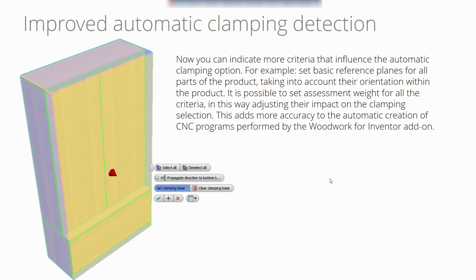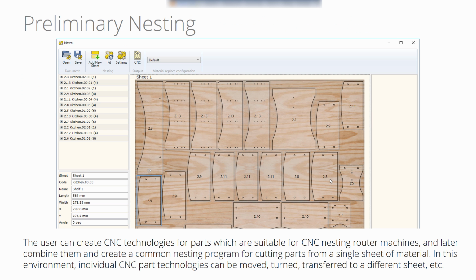There is a weight system, or a priority system, which allows you to say, for instance, keep the holes as near as possible to the zero coordinate of the CNC machine, or place pockets as near as possible to the zero coordinate of the CNC machine, and so on. So you can balance between those to find the right situation for you, because many companies focus on one kind of furniture. They can find the balance and adjustments most suitable for them, and then use it in future designs.